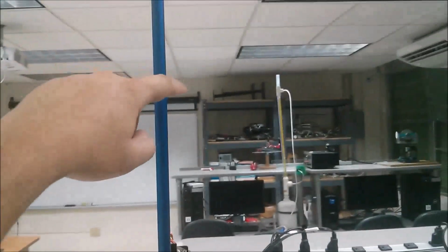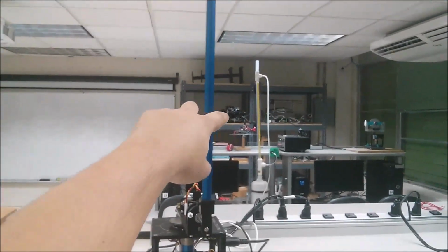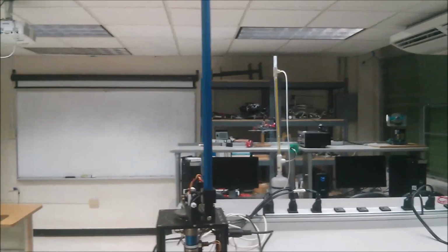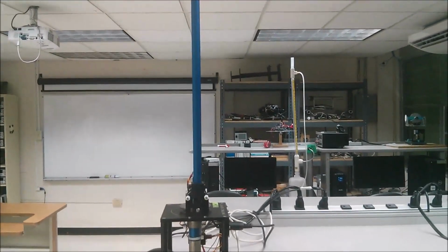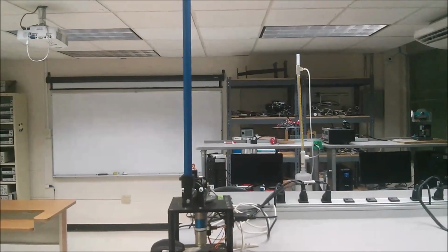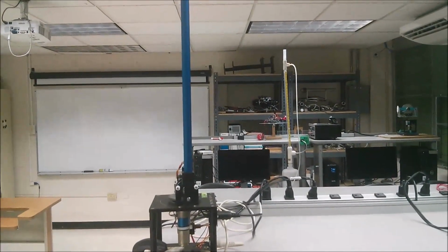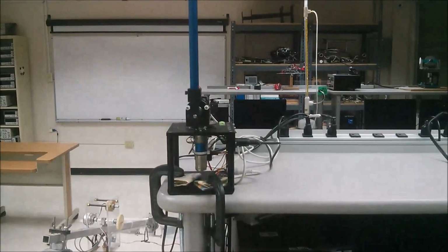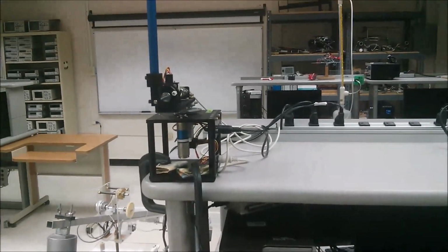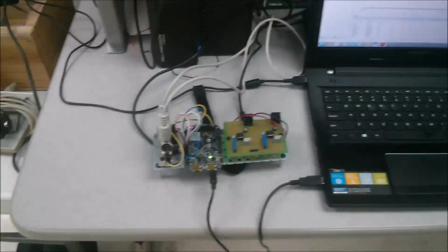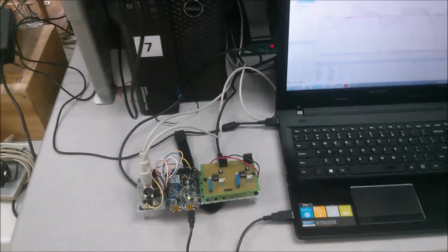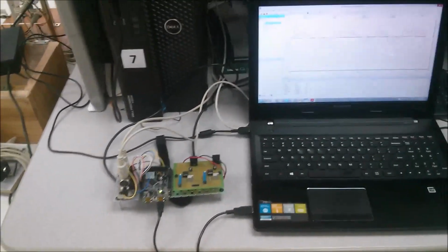This is a state space design using a Kalman filter, and we implemented it using the Kinetis Design Studio, and we made all the matrices calculations in C code, and we developed the controller using Matlab with the functions lqr and lqrd.